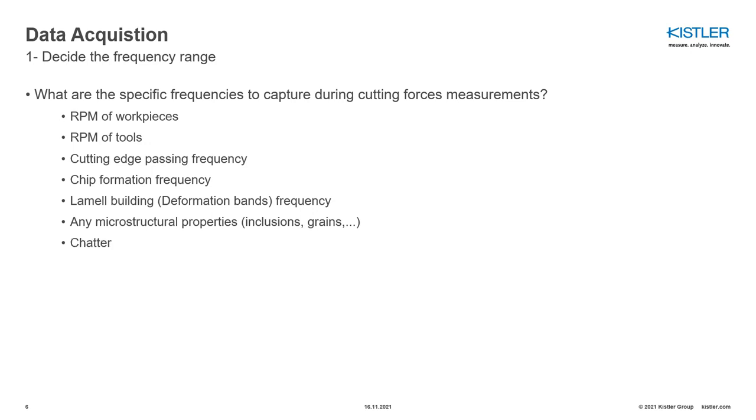Chatter, of course. Cutting forces also consist of the effects from any vibration coming from the machine or the spindle or the linear moving axis or the process excited and so on. So that effect can also be captured in cutting force measurements.